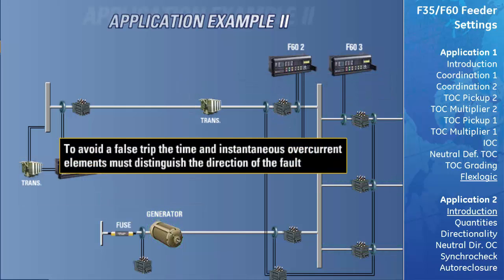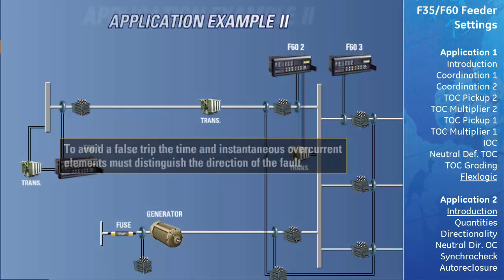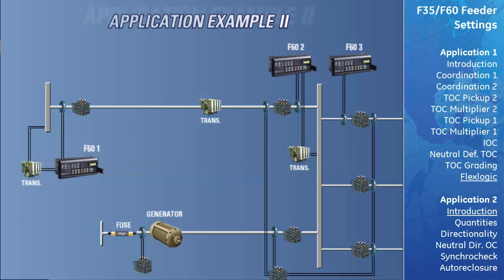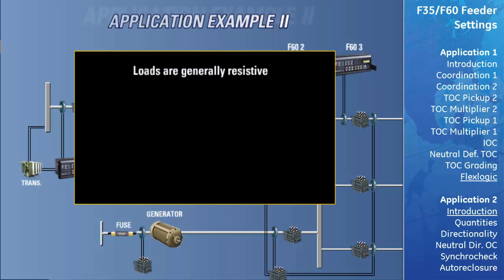To avoid a false trip, the protection requirement for this application requires that the time and instantaneous overcurrent elements be able to distinguish the direction of the fault. We will now explain the theory of directional overcurrent elements and then apply them to our protective solution.